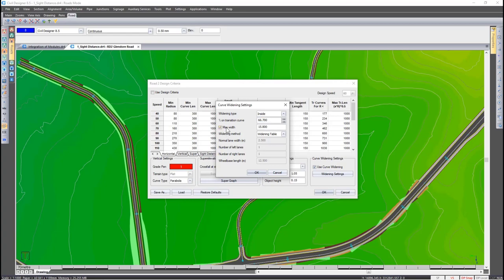If your road has transition curves, the full widening will be applied to this specified customizable percentage. A maximum width is useful in restricting road reserves. Three widening methods ensure that you are not limited to choice. As you select which method to use, the applicable cells below are made available for customization. I'm then going to select the widening table option to discuss this in more detail.